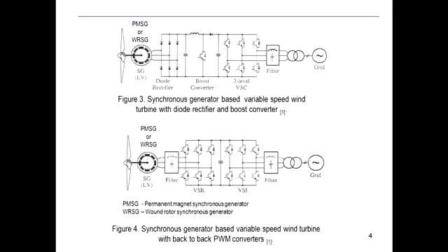And if power factor is poor, you know that the current supplied is higher than what it can be, all right? So if you can run it at unity power factor, then the current drawn per kilowatt is the minimum, all right? So the attention here is how to run the machine with unity power factor and extract power. Okay, normally we run this converter with a certain power reference and 0 reactive power reference. All right, if you put 0 reactive power reference, then it becomes unity power factor operation.